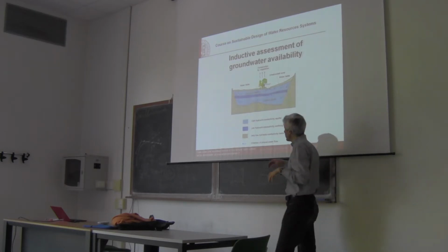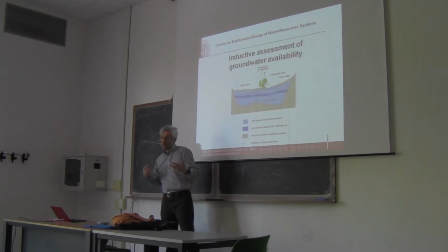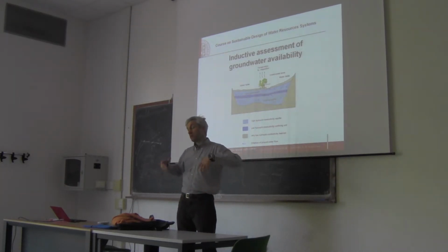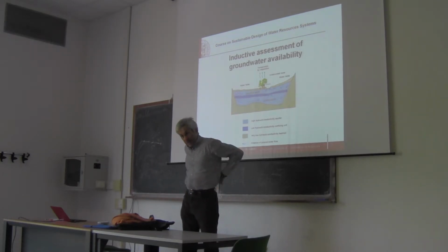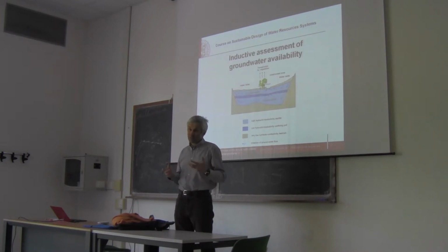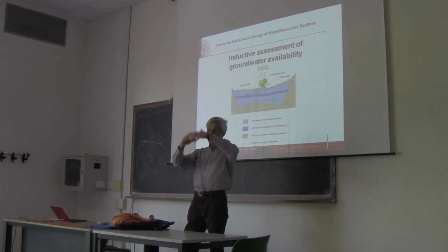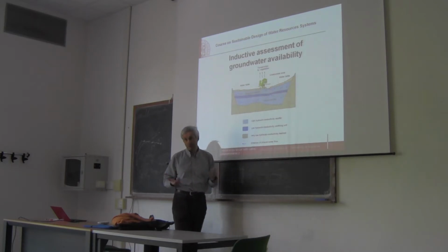And as I said, the confined aquifer is even more difficult to understand because the recharge typically takes place from far away. And given that it's under pressure, it's not so easy to monitor its status, because we see water coming out spontaneously at the surface, and we don't notice whether the total storage of the aquifer has decreased or not.